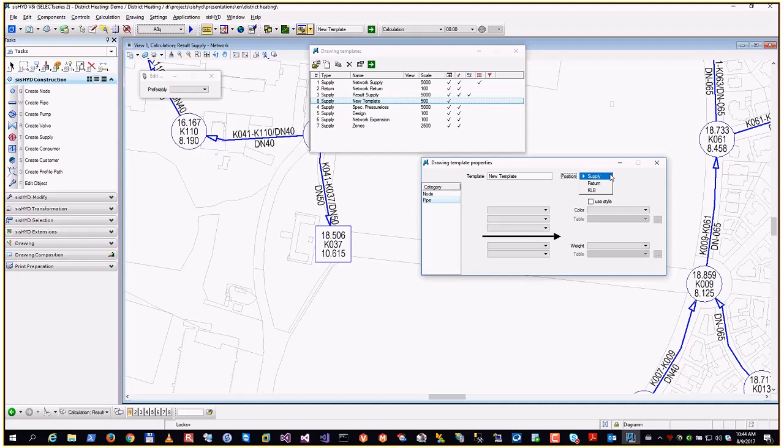Yeah, three pipe, it has one return in common and one supply for the heating and one supply pipe for the tap water. So the motivation in history was that in summer times you would not use the heating part. And you distribute the flows for supply to two pipes. So in summer times you have still reasonable flow rates and flow speed in a pipe.